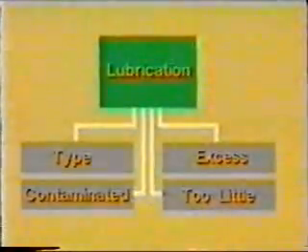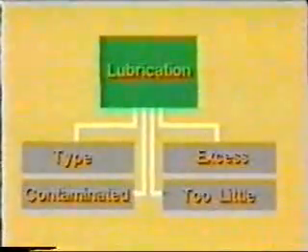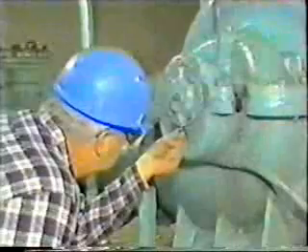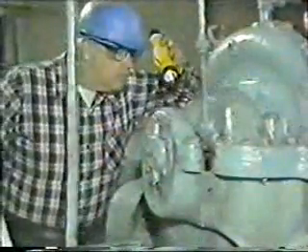Gene didn't see any bits of metal or feel any dirt. He thinks that contamination is not the cause of the problem. He has checked for excessive grease, and earlier he checked to see whether the seal was leaking, but the problem could still be too little grease.